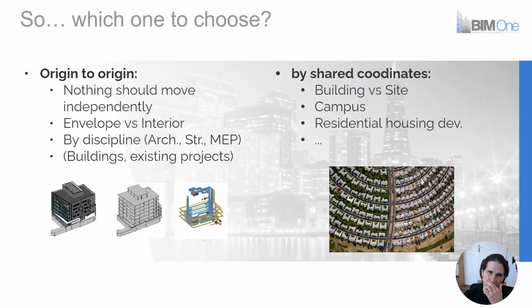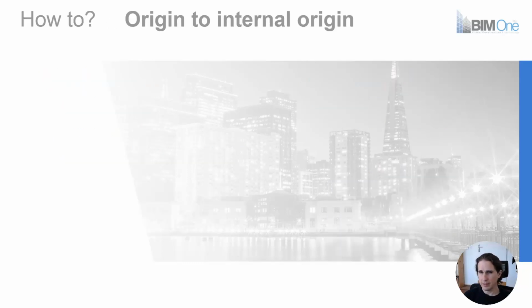We can often start a project by linking origin to internal origin and then switch to by shared coordinates afterwards, once the site plan from the surveyor has been received or the position of the building established on the site.